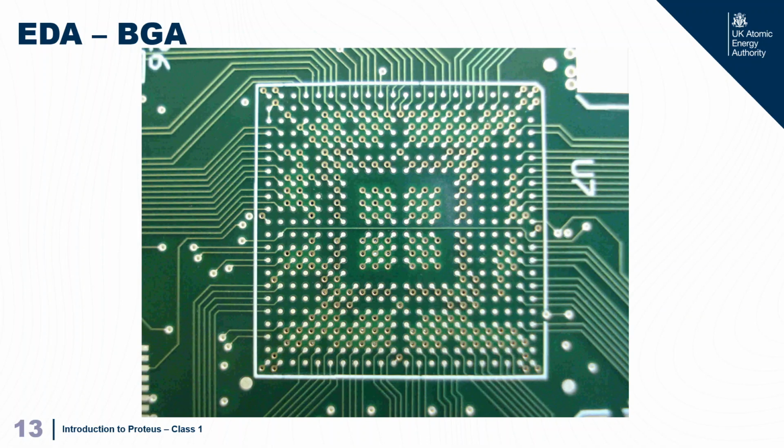So this is what the actual board looks like of the BGA package. You can see the pads, which are the shiny silver bits, and you can see all the vias, sort of perforated within the package. There's this thing called fan-out. These two top rows, you can see that you can route the traces into the package from 2 rows. Whereas for the next 2 rows, how are you going to route those traces out? You've already taken up all the space on that layer. So you had to access the next 2 rows in. So these 2, you have to go to another layer, and then another layer, and another layer. That's how you access these things.